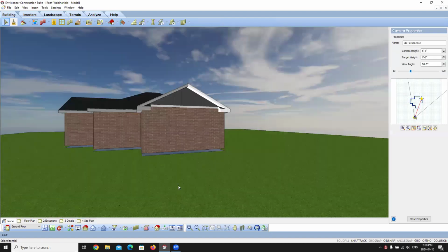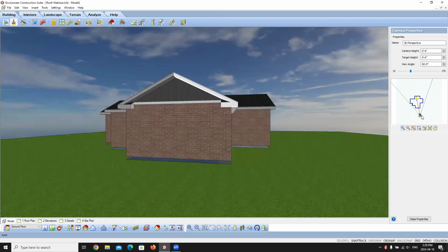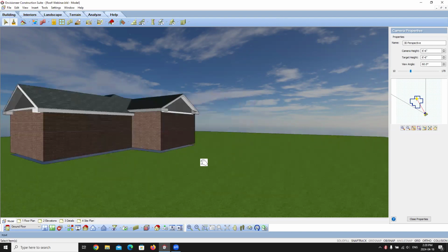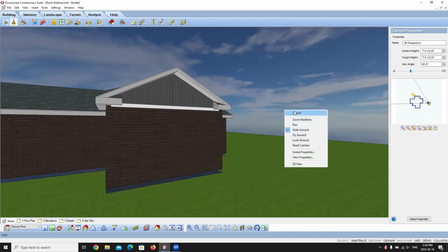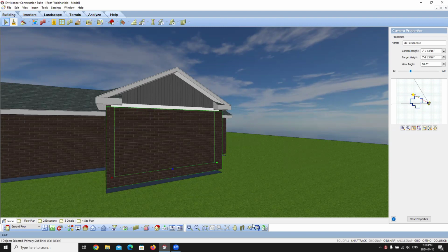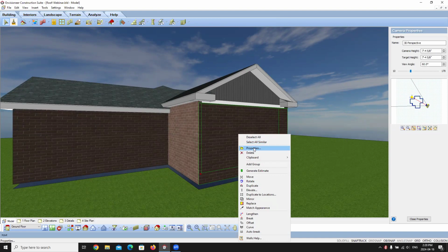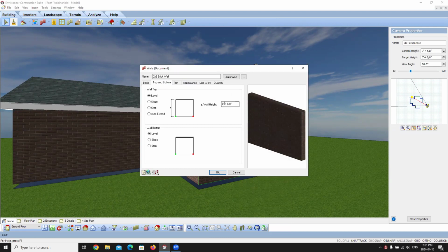And if we go into a 3D view, if I pull the camera around to that side, we can see that the edge of that roof is now higher than the rest of the roof. Now the walls themselves, we may need to adjust those because that's going to be set to the 8'1 1/8". So if I want these walls to be a little bit taller, I will need to adjust these walls so that their properties match. So in the properties, we would say top and bottom, this should be 9'1 1/8". Actually, we'll just say 9 foot.